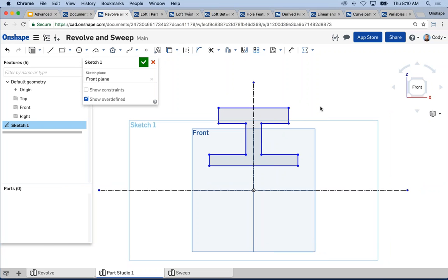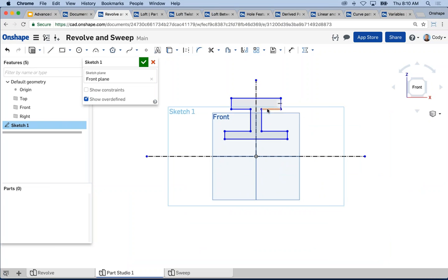And this is an important thing when we talk about revolve profiles. Remember, this is going to be a round part. And in my case, a full 360-degree revolve, creating a full round part. So when I go to add dimensions, adding a dimension like this isn't really helpful in most situations. I don't really want to define a round part by radius values throughout the entire thing, right?